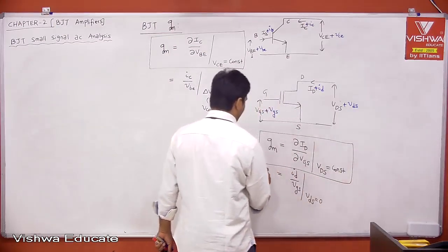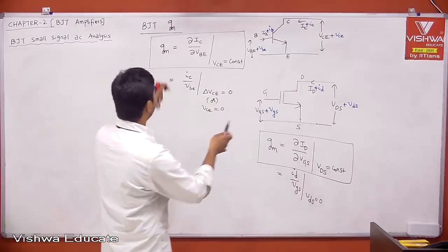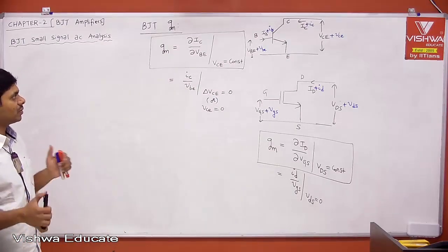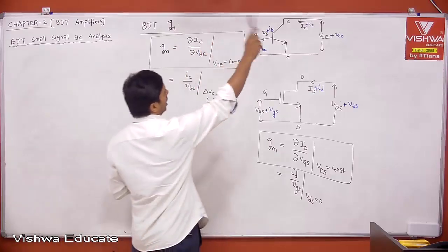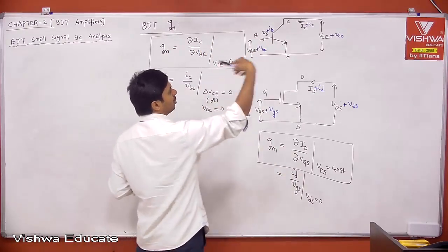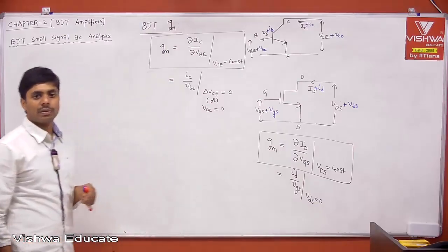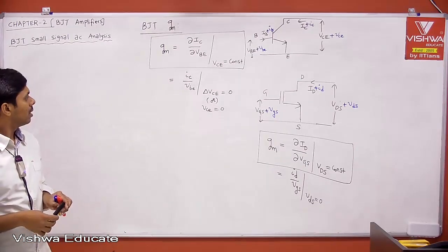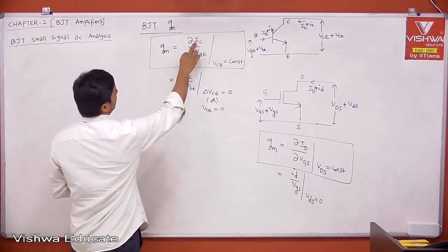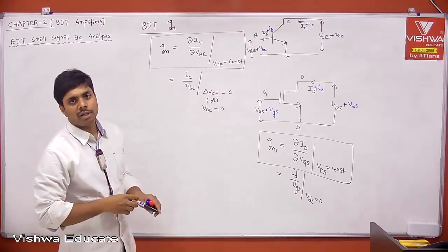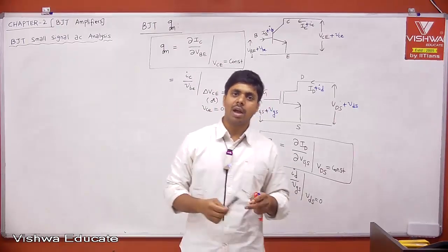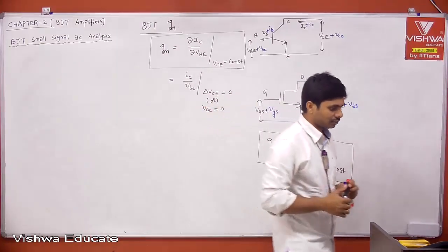Anyway, this is what I am going to use later. But just to correlate between BJT and MOSFET, I explained that, irrespective of anything, the definition of GM is the change in output current because of the change in input voltage only. When I say only, it means keeping all other voltages constant. That is the meaning of it. Okay. Then we will derive, because we know IC is equal to alpha into IE plus ICBO. Then we can differentiate and we will get the relation. Okay.